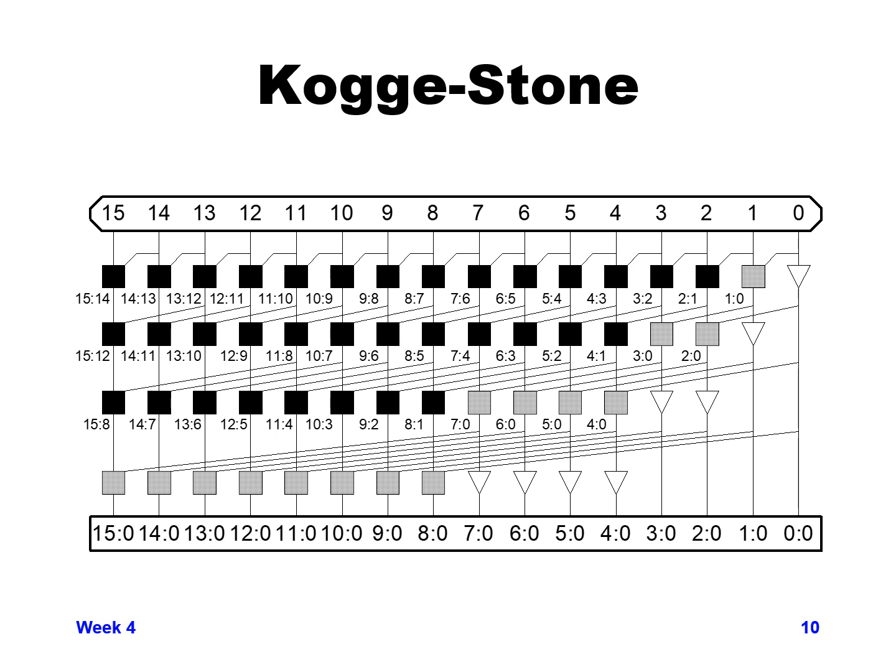So the Kogge-Stone design or adder tree is using a similar way of trying to calculate the large tree combinations and small tree combinations at the same time that we just talked about on the previous foil, as well as only doing a fan out of 2 for each stage that we had talked about 2 foils ago with Brent-Kung.